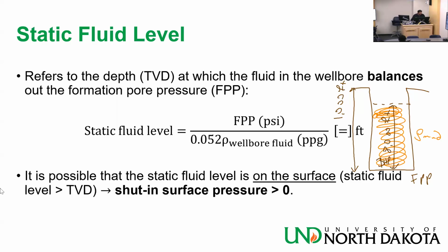Sorry, 10,000 feet. So I don't need the whole well filled with mud to balance the formation pore pressure. I only need 8,000 feet. So my static fluid level is 2,000 feet from the surface, or 8,000 feet from the bottom hole, right? Just a hypothetical scenario here.